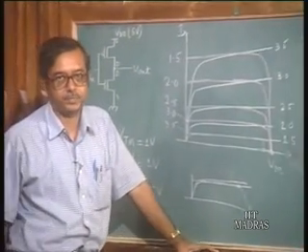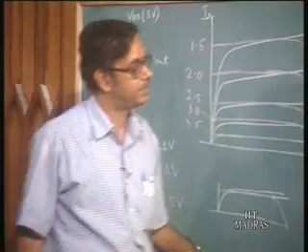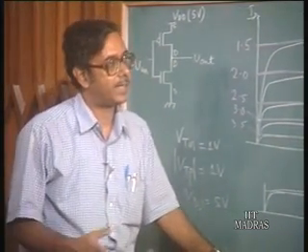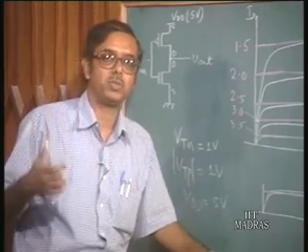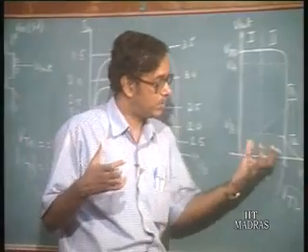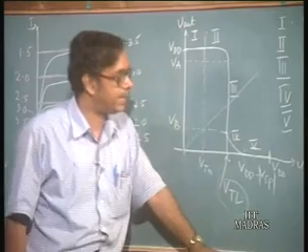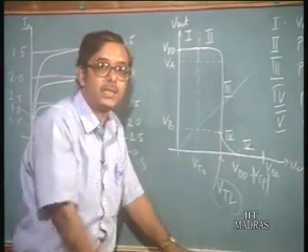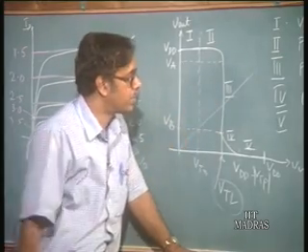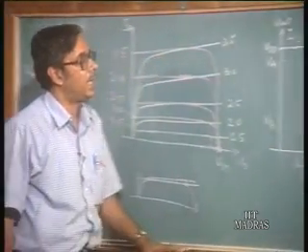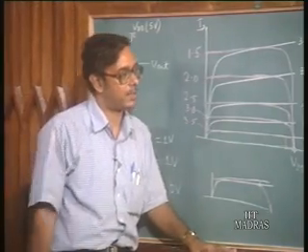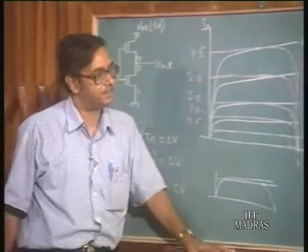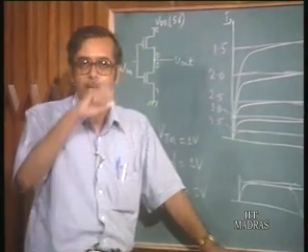which is the desired voltage. So, we see that for the CMOS inverter we have input-output characteristics which are very close to the ideal inverter characteristics, and again this logic threshold can be adjusted to Vdd by 2, so that we have almost equal noise margins, and so again we get very good characteristics. All right.